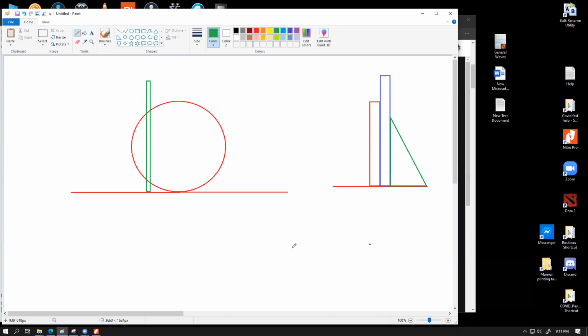In this part, I explained elaborately how to make sure the coils are perpendicular onto the bench, and to measure the gap in between them. I said that we would measure their gap with a meter rule or with a predefined spacer in multiple different places so that they are exactly equal distance from each other.